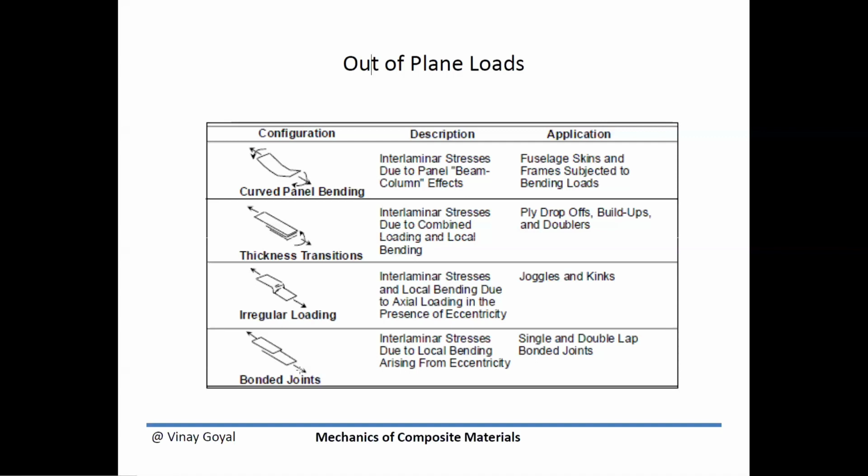But in general, interlaminar stresses would be quite high in these situations, and they will arise from the eccentricity in the load, but also due to the mismatch in the different materials' modulus. This kind of situation will be encountered in lap joint situations.